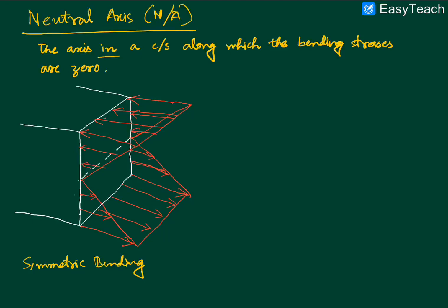So in connection with this neutral axis, there's a very interesting point. It's such a nice and clean point that we can almost write it like a theorem. And this theorem says that as long as a beam is subjected to pure bending, and this is very important, the neutral axis will always pass through the centroid of a cross section. So let me write that down.